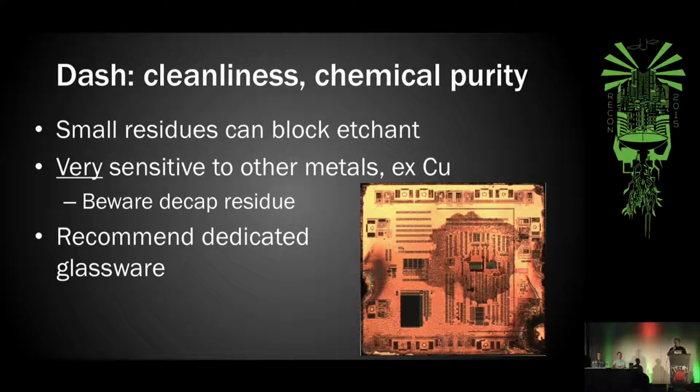Another issue I found was I was using the same beakers for doing the decapping as for the hydrofluoric acid etching, and the problem is that nitric acid will react with copper very readily, which is present as the lead frame in a lot of these chips. And what this does is it creates this copper nitrate, which then interacts with the hydrofluoric acid to cause a lot of side reactions that will kind of copper plate the die and basically stop this reaction altogether. So use dedicated glassware, and things started working a lot better.